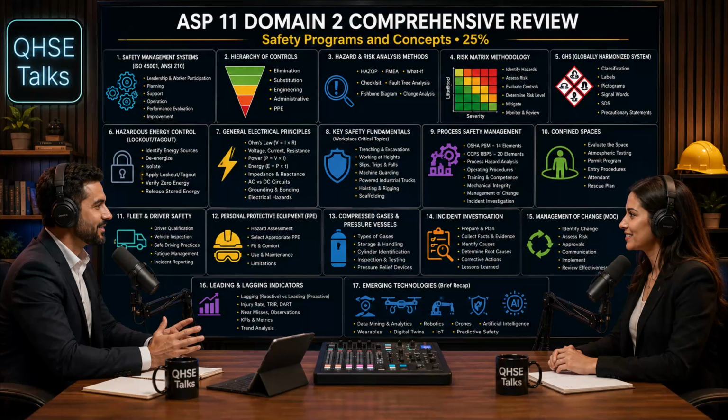A standard oxygen cylinder holds gas at over 2,000 pounds per square inch. That's a massive amount of pressure. If that cylinder falls over and the valve snaps off, the rapid expansion of gas governed by Boyle's law turns that heavy steel cylinder into an unguided missile capable of punching through cinder block walls. This is why cylinders must be chained upright at all times and stored with their protective caps on.